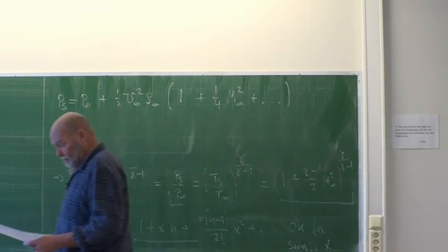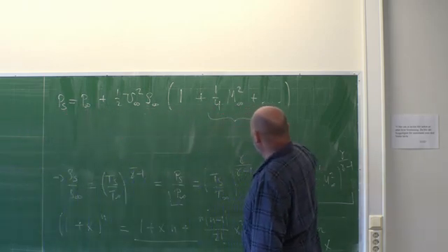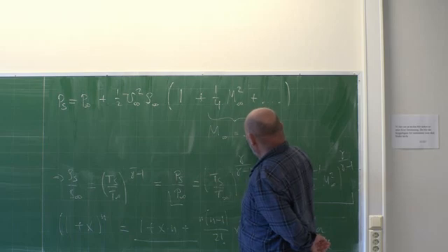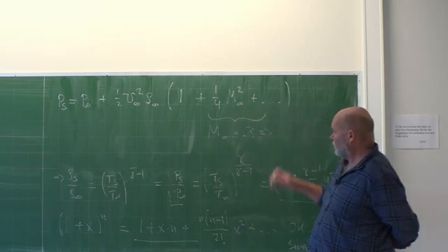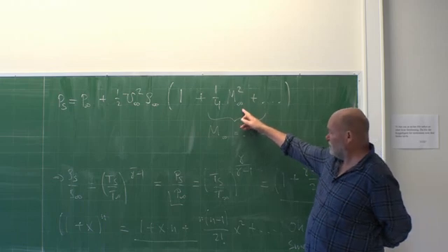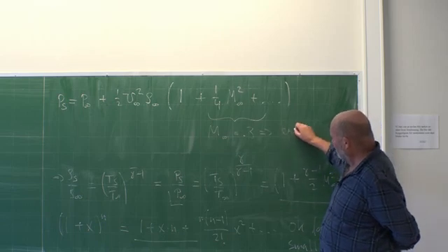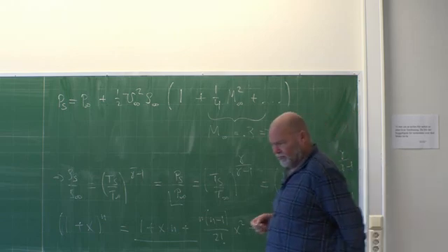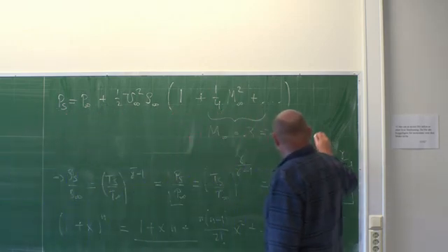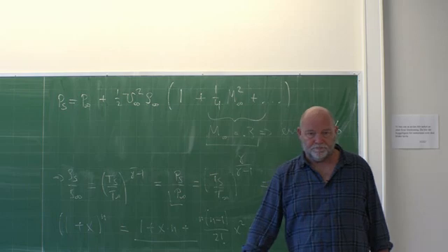So here is then the point. If I have a Mach number of 0.3, what will I get here for this term? Well, you have 0.3 times 0.3, it's 0.09. Then you take a quarter of that one. So you have, which then will be 2% or something, wasn't it? Yeah. About 2%. That is where we have this limit, Mach number 0.3.